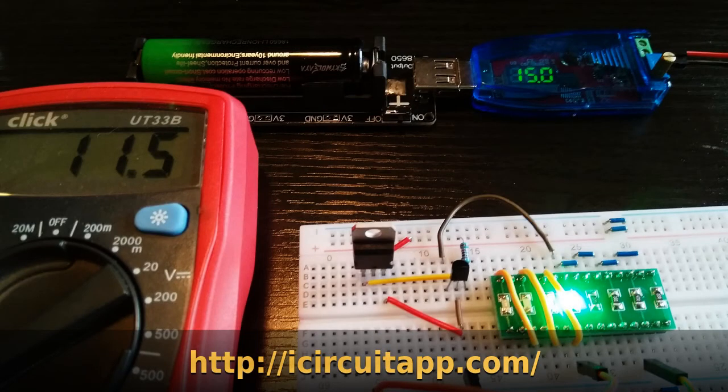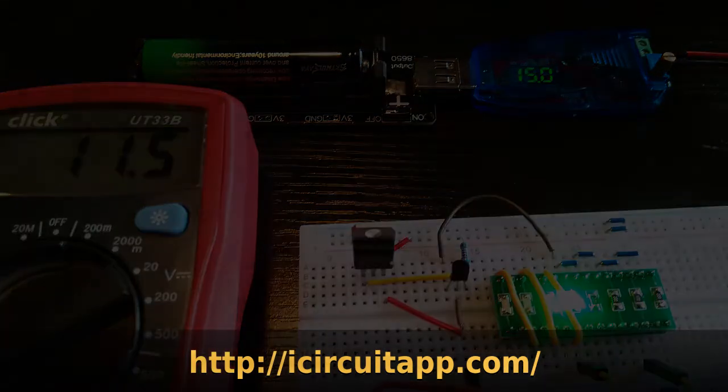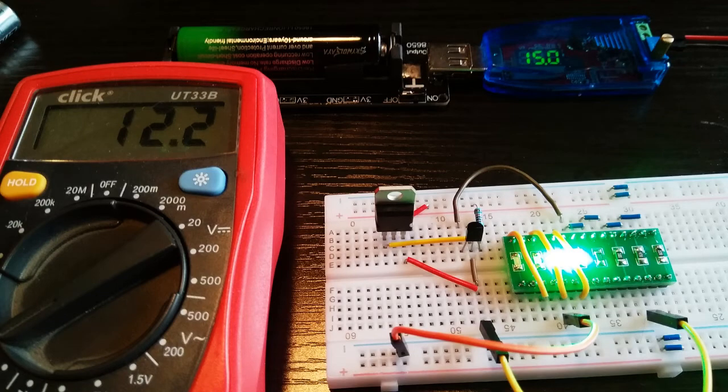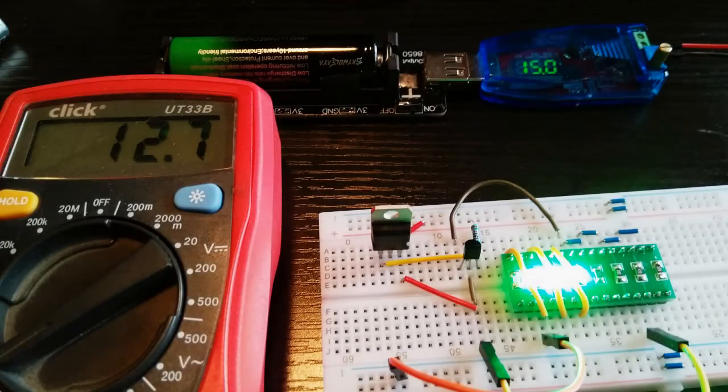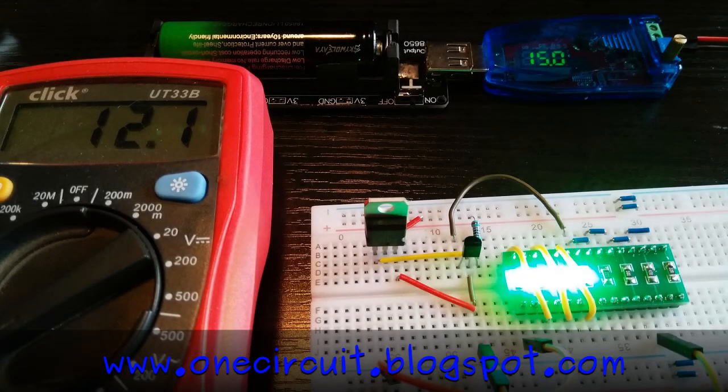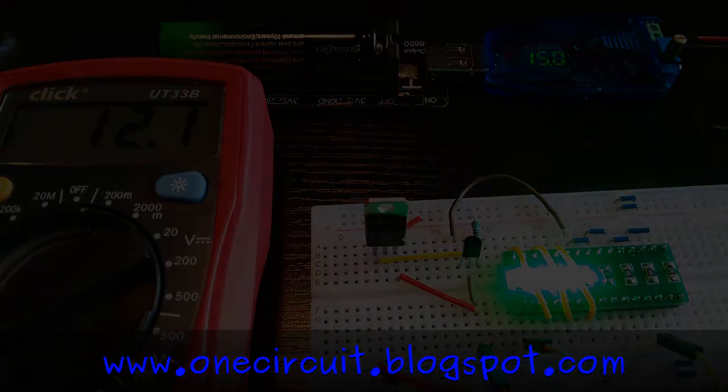Now I've changed the resistor, so this is a higher current and 1 LED, 11.5 milliamps. So this is the R2 value changing to give us the higher current, and this is 12.2 milliamps with 2 lamps lit. 3 lamps, 12.7 milliamps, 15 volts, and that's 12.1 milliamps and 15 volts. Yeah, so it's 47 ohms, that last one.